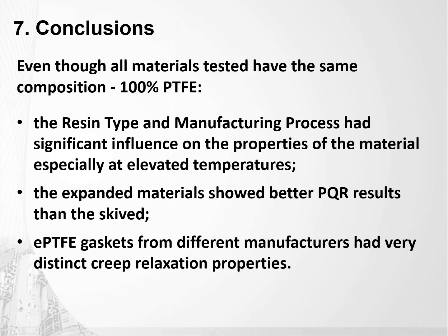Going to our conclusions, even though all materials tested have the same composition, which is 100% PTFE, the resin type and the manufacturing process had significant influence on the properties of the material, especially at elevated temperatures. The expanded material showed better PQR results than any skived tested. And the ePTFE gaskets from different manufacturers had very distinct creep relaxation properties.